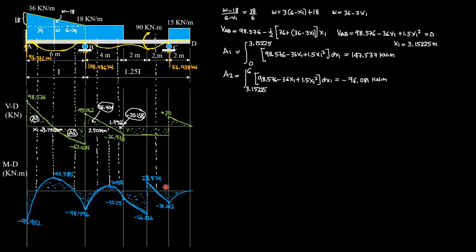So this is the moment diagram, and we project this upward to find the points of inflection, or points where concavity changes direction, here and here. In this portion, we have negative moment, concave down, elastic curve. This portion, positive moment, concave up. Then from here up to here, concave down through the support. Then we have positive moment, so concave up again. Then negative up to here, concave down. Then we have a positive portion here, concave up. And finally, negative moment, concave down up to the end. So that's it. That's the elastic curve for this beam.